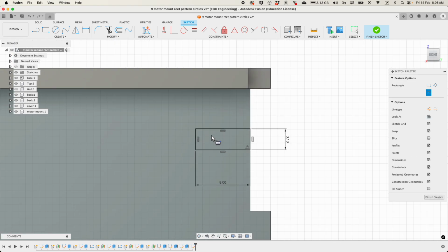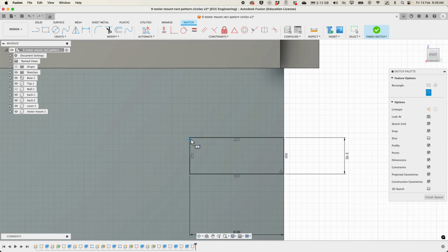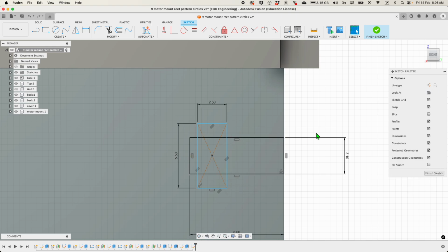So obviously these are captive nut joints that we're doing, and they are designed to be used with an M3 10mm bolt. If you're using a different size bolt, you would want to amend that to what's required on your end, but that's what I'm using. And dimensioning that, and that's going to be 4.5, enter.